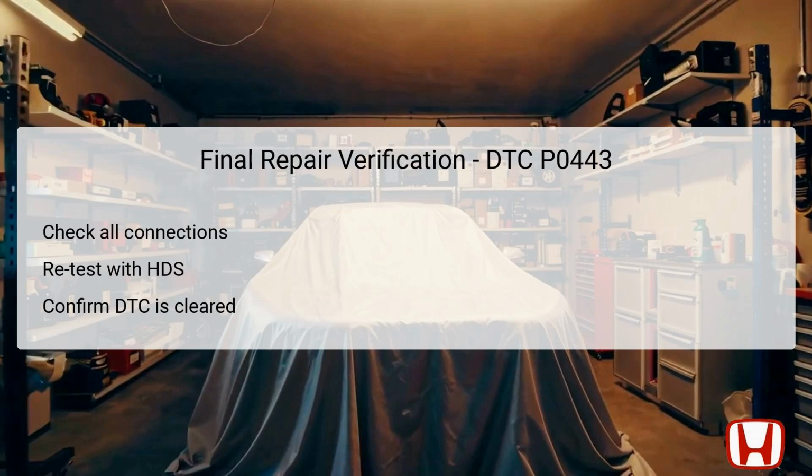Upon completing the necessary repairs, it's critical to conduct a final verification step to confirm the effectiveness of your work. Begin by checking all connections again, ensuring that everything is secure and properly installed. Follow this by retesting the vehicle using the Honda Diagnostics System, HDS, to check for any remaining or new DTCs.